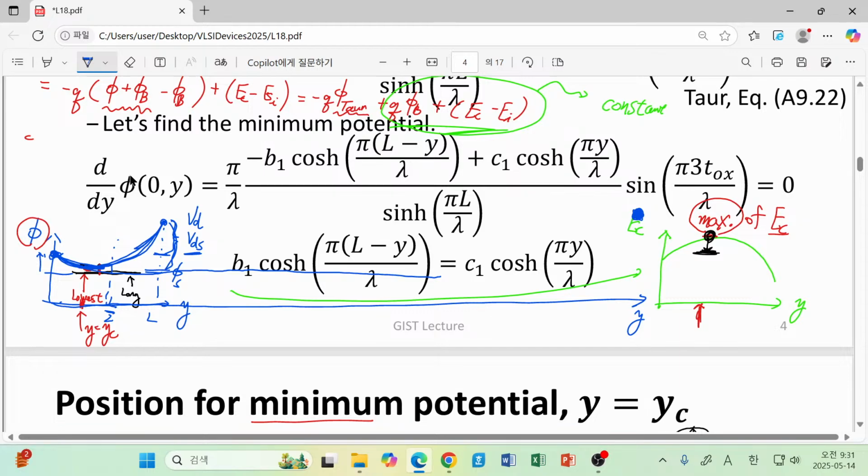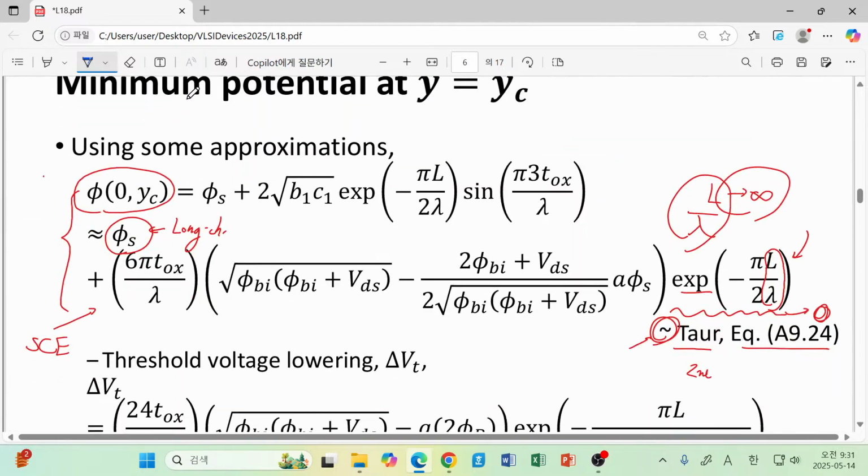Also here we have its own decrease behavior. However, that will take a few lambda scale, but it will be gone anyhow, and we have plenty of long length scale still, corresponding to the full long channel approximation. So the value becomes just phi s. That's the reason why we have a vanishing short channel effect term.